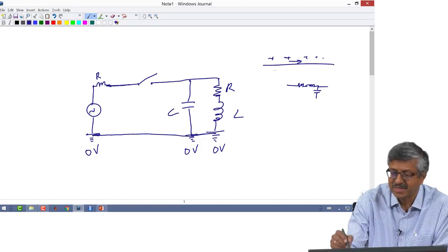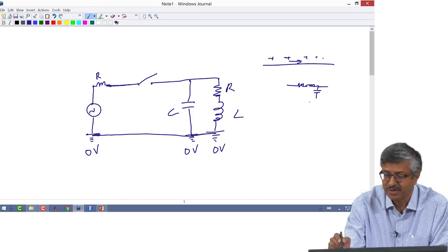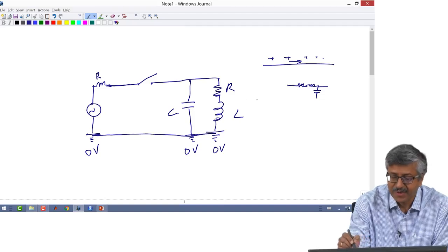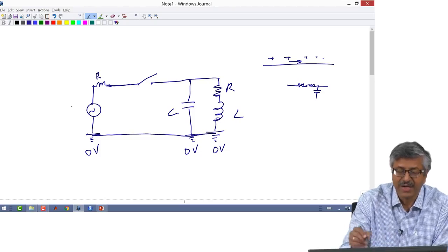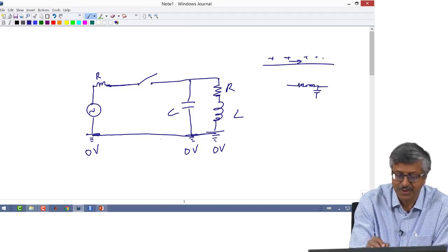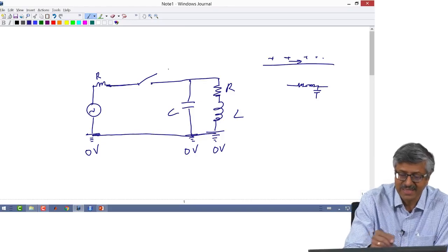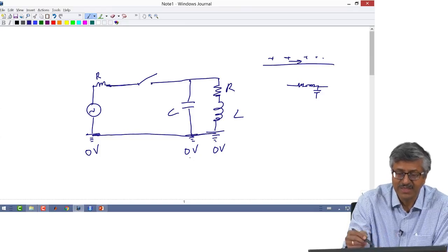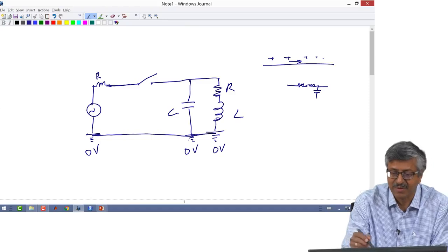So what we call a plain conductor of 0 impedance is actually an impedance network under high frequencies, when frequency is increasing, not for DC. Even for DC you can have some resistance, of course. Then the capacitors also are not ideal. So your real circuit under high frequency is much more complex than what we see over here. You can have a potential difference between this point and this point because of the impedance of this conductor. So it is these things that we are coming into by describing the non-ideal behavior of each of these components. The concepts developed here will be used in chapter 4, while talking about crosstalk and other interference coupling mechanisms.